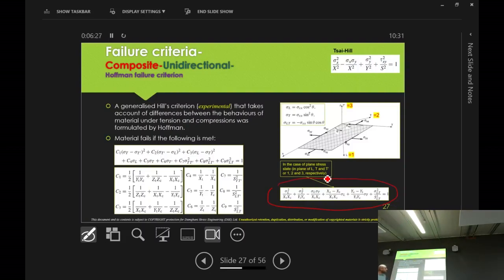Longitudinal, transverse and longitudinal. So that essentially is stress in the fiber direction divided by strength. So these are stresses in the fiber direction, whereas that one was in the loading direction. Okay, that's different. But you can see it's a bit more comprehensive than the Tsai-Wu. So we're getting there. As time goes by, these formulations become more advanced.